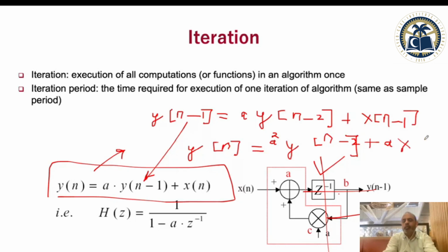You're not really concerned about the feed forward part of this equation, because that does not really hurt. You can always delay this, n plus x of n. This is a very neat technique, that now instead of having one register in your cloud, you have systematically put two registers, and two registers can help you to break your critical path into three pieces.